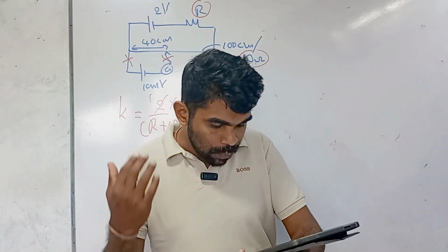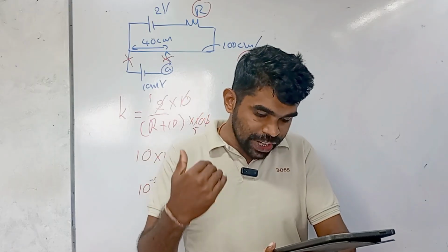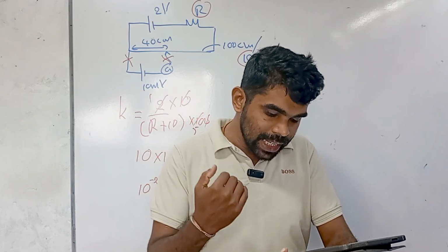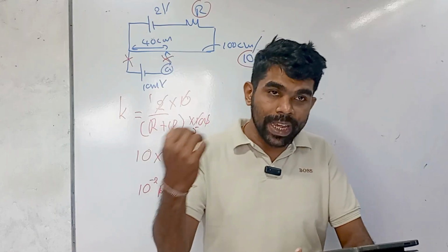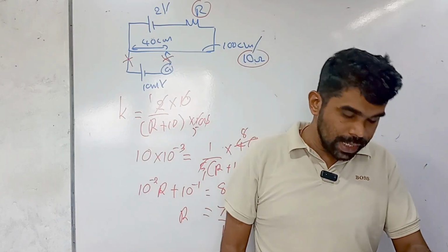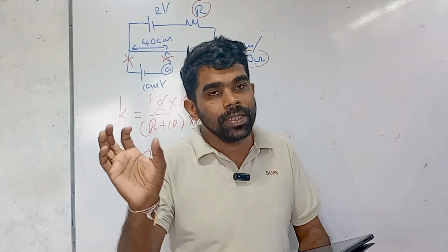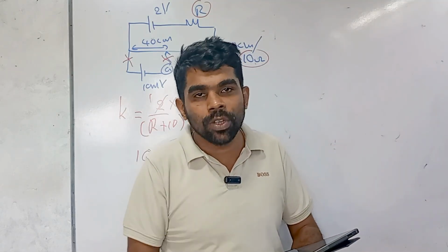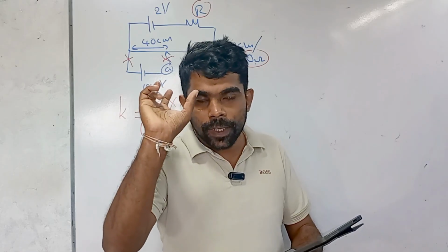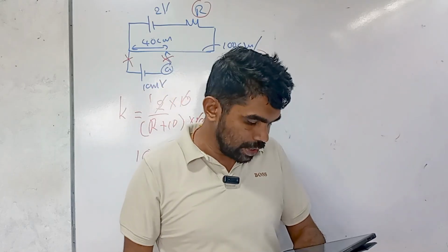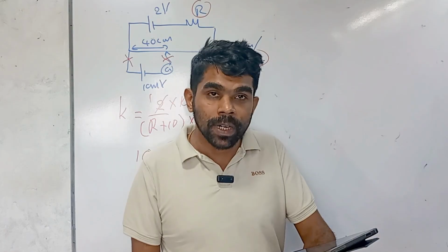Then the second one, the voltage drop across each resistor in the set of series resistors is the same. We can consider the set of series resistors. For series resistors, current is constant, but the voltage is the same only when the resistors are the same. Therefore, the second statement is false.